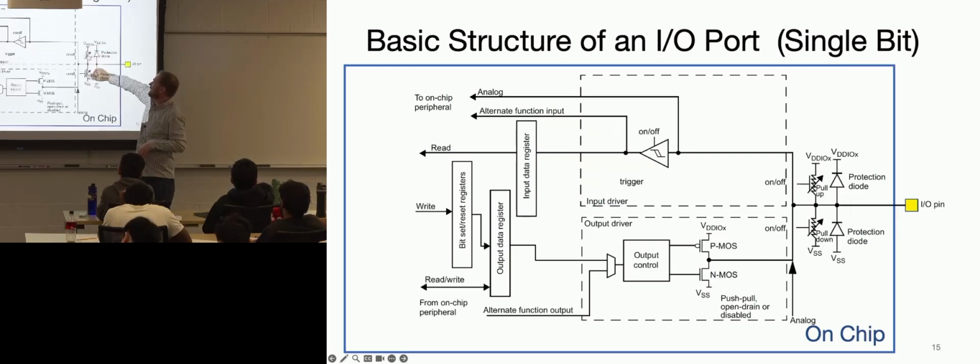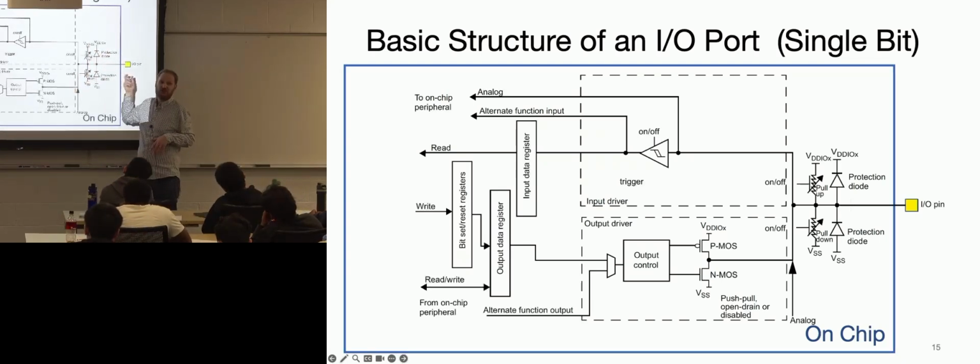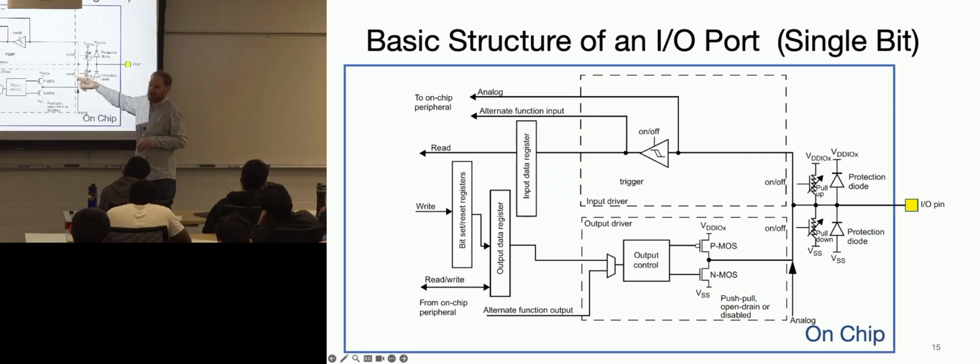So here I'll tell you why you'd want resistors at all, and that is for some communication protocols we'll talk about later, you can have it pull up on its own without having digital logic to do it. The trick is, why would this company choose to put resistors, which are physically large, on chip? Physically large resistors mean lower profit margins because you have more silicon. So why would a manufacturer put resistors on chip that somebody could put outside the chip? Tampering? For tampering?